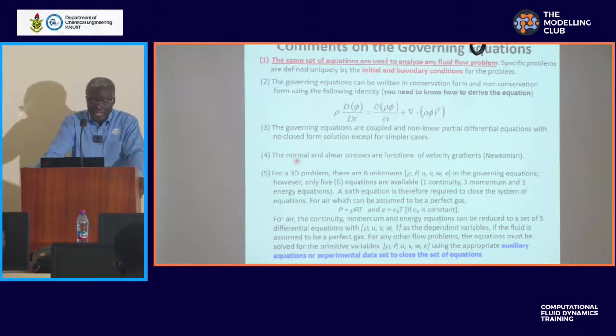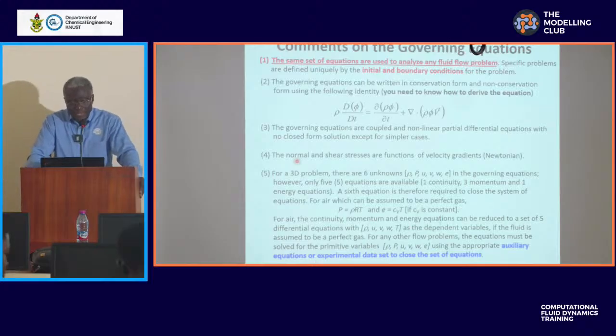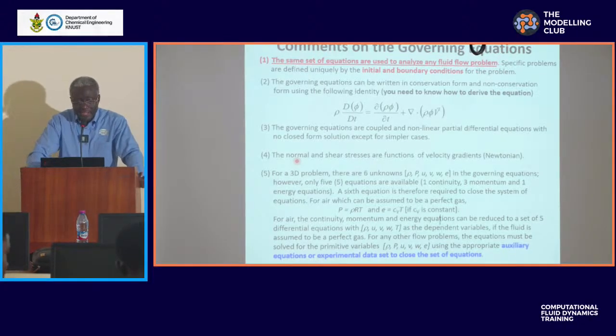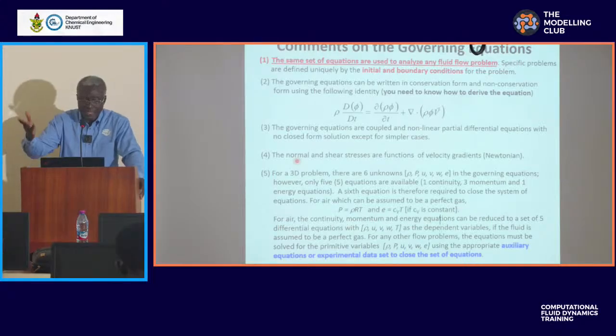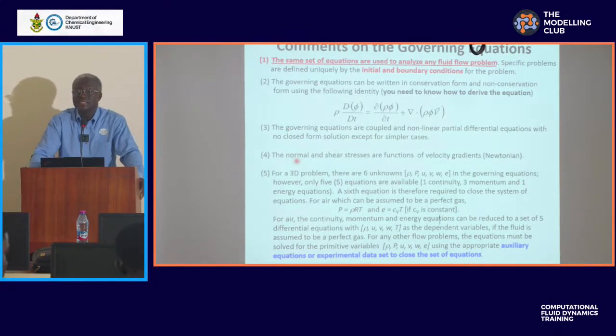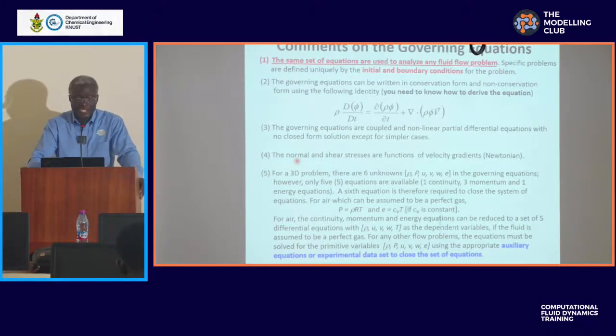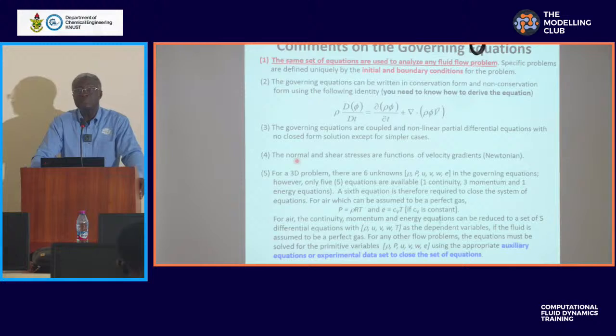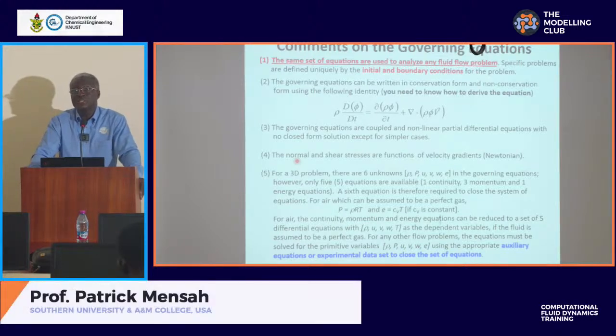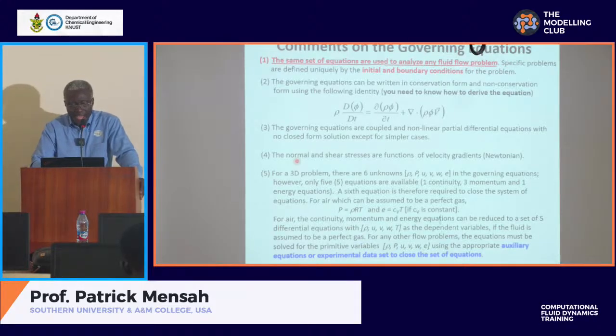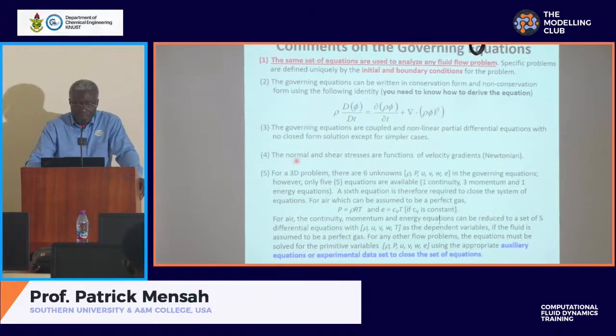Well, the 6th equation is required, for example, if the air is an ideal gas. You use rho R T to replace pressure in the equation, therefore eliminating the P term, and you replace the E, internal energy, with your specific heat at constant volume times temperature.